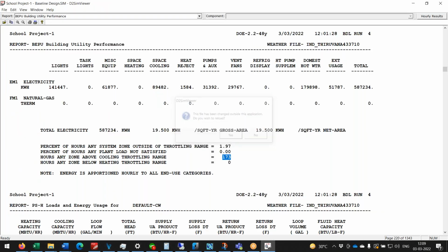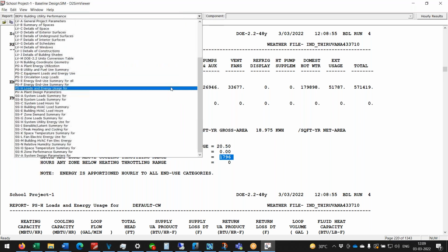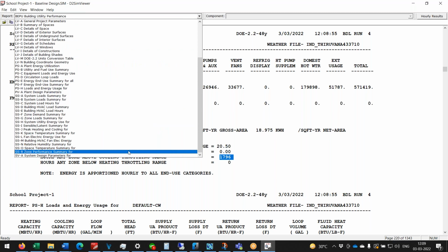The capacity is found in, yes, now we have 1796 throttling hours. Okay, so that means increasing the insulation is actually detrimental. If you have a high heat load, it's trapping the heat inside. And in fact, let's look at which zone we have throttling. First, we need to eliminate throttle, then we can go for